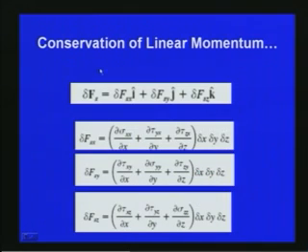So now with respect to the surface forces, if you take the ijk, that means the xyz direction, we can write the total surface force delta Fs equal to delta Fsx i, with respect to the ijk triad, the unit vector i, plus delta Fsy j plus delta Fsz k. So now we have seen that for this particular fluid element there are three components, x, y, z, for the surface force.